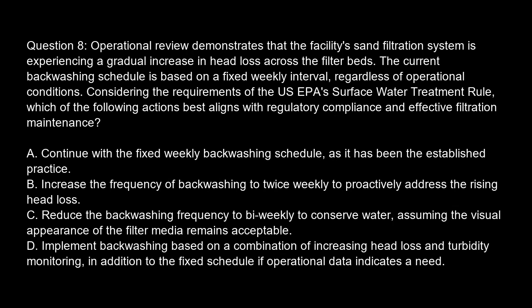Question 8. Operational review demonstrates that the facility's sand filtration system is experiencing a gradual increase in head loss across the filter beds. The current backwashing schedule is based on a fixed weekly interval, regardless of operational conditions. Considering the requirements of the U.S. EPA's surface water treatment rule, which of the following actions best aligns with regulatory compliance and effective filtration maintenance?